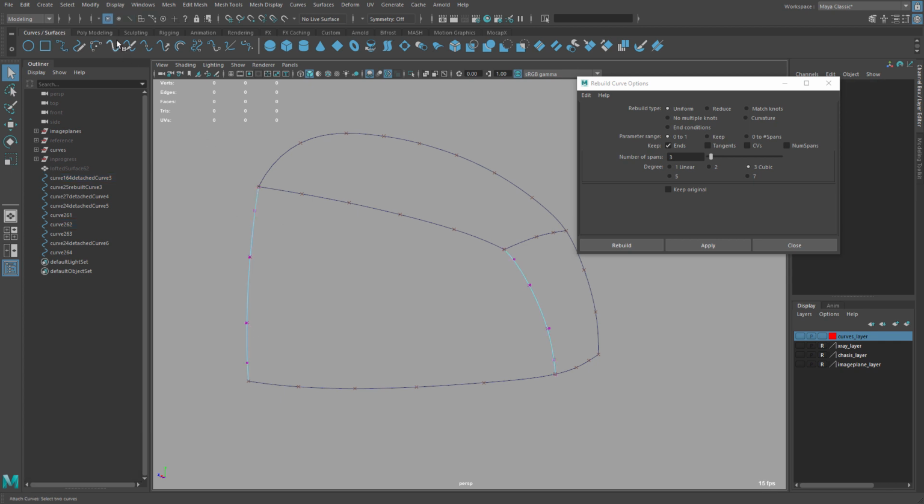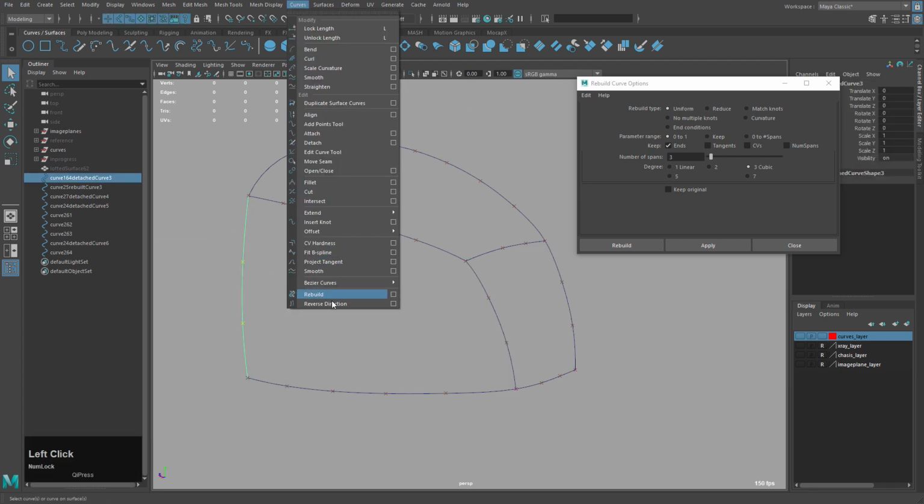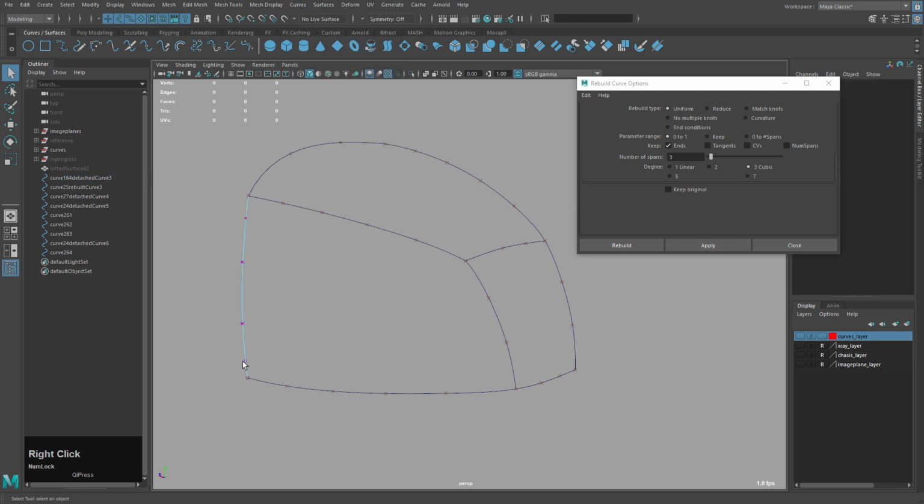If you don't see vertices, just turn on and off the vertex selection. You can see that these curves, the U and the square on the bottom, so that's the curve direction, that's where the curve starts. This one, it's reversed, so I just need to select this one, go to curves and click reverse direction. Now you can see the U is on the bottom,